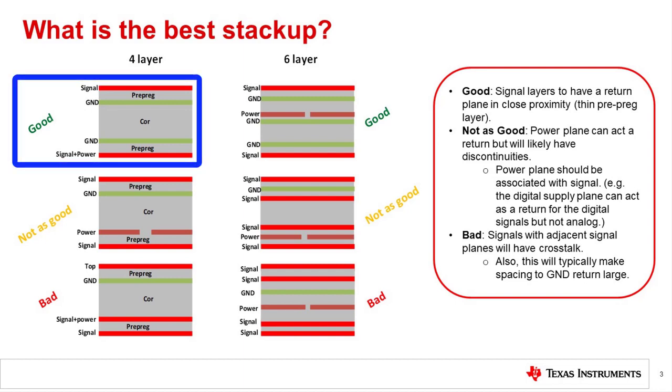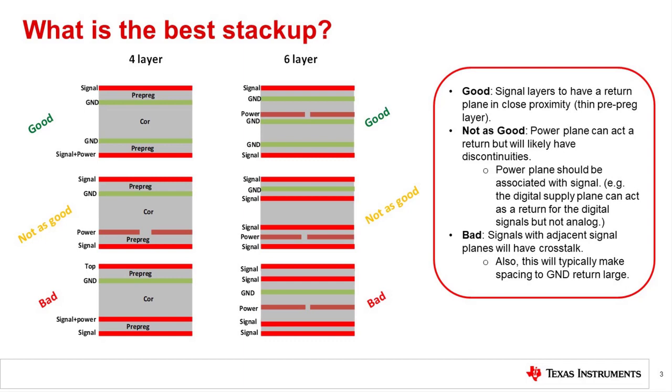The best approach for good EMI on a 4-layer board is to use 2 internal ground planes. In this case, signals would be assigned to the top layer and power and signals would be on the bottom layer. This method has the advantage of keeping the power rails very close to the ground return path, which will improve decoupling. This method also eliminates the need for stitching capacitors as the ground return is solid, whereas the power plane in the previous example was split to accommodate multiple power rails.